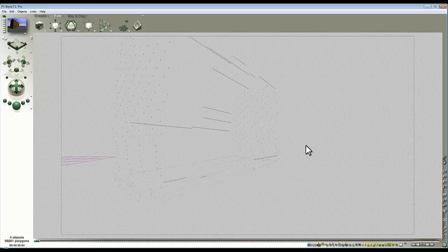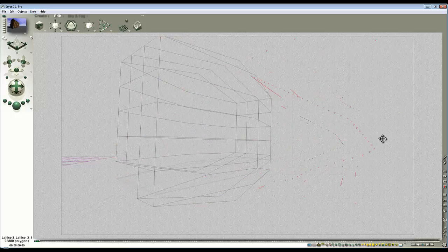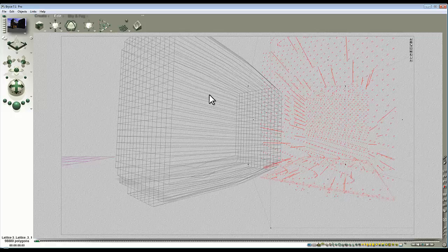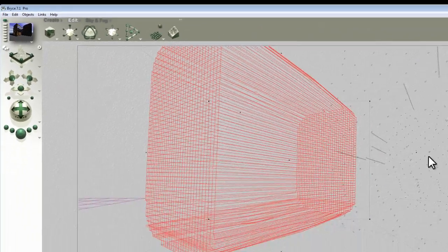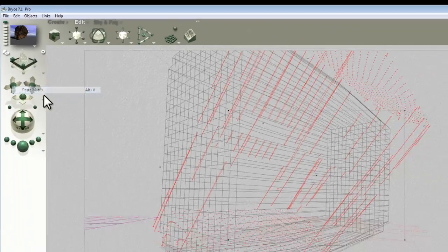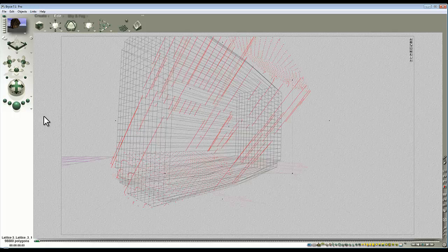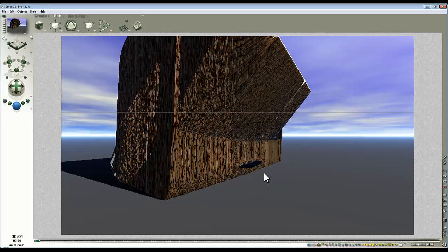You might be wondering, those of you more familiar with Bryce, why I didn't use copy matrix. If I just Control Z back to bring my original lattice in here and get hold of the imported one and move it to one side, select my original one, edit, and go copy matrix, and then select the new lattice and go edit paste matrix, you'll see, I hope, that the matrix tool has not worked with this.